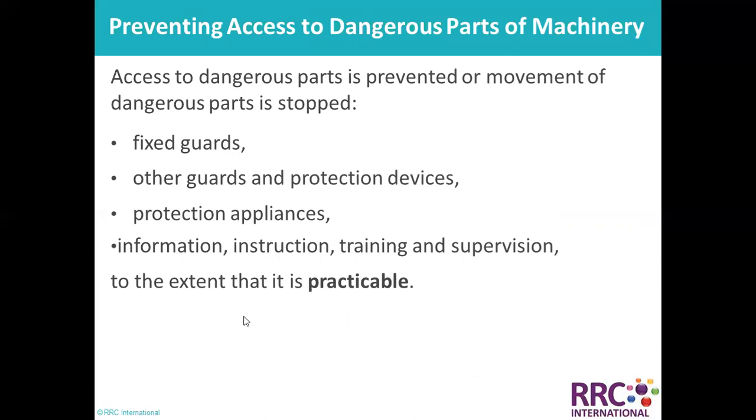Now, how are we gonna prevent the access to dangerous parts of the machinery? Because access to the dangerous parts is prevented, movement of dangerous parts is stopped, like through fixed guards. And with these fixed guards, you just need to make sure, because sometimes I noted personally, you just had a fixed guard, but unfortunately later on it is a big trouble because you are unable to access several areas of the machine. So fixing the fixed guard, you truly have to have a detailed evaluation before,